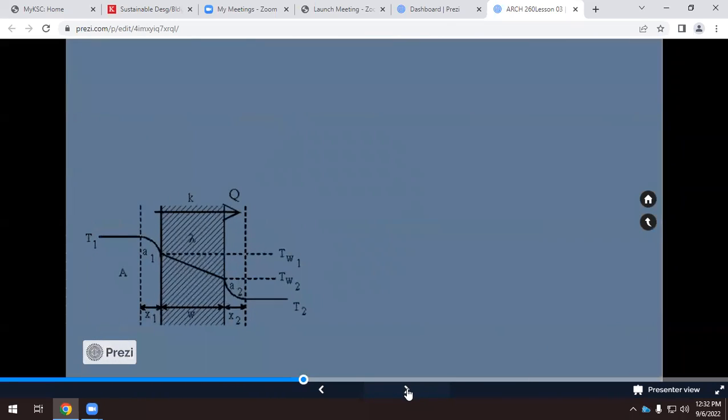What's next? Well, as I told you, we have different layers in walls. It's not just a material. You see that outdoors we have brick, and indoors here we have this finish, this plasterboard, and in the middle there will be other materials. At least we need the thermal insulation. So at least we need 3 materials in a wall.